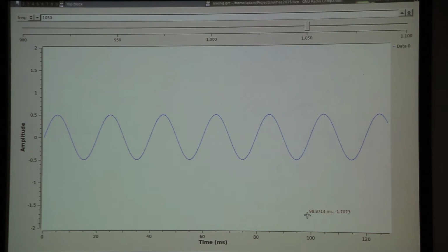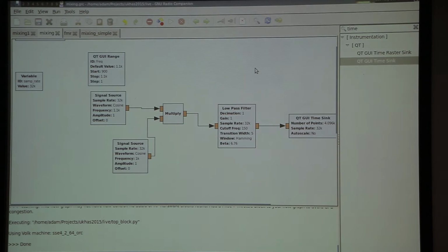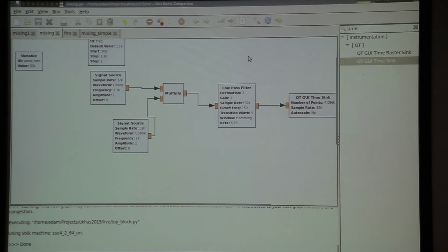So the way we resolve this problem is by taking an additional measurement of a signal, basically. We want to know its phase as well as its amplitude, so we have to record something else. And the measurement we take is, instead of multiplying it by this local oscillator, we take the same local oscillator and shift its phase as well.